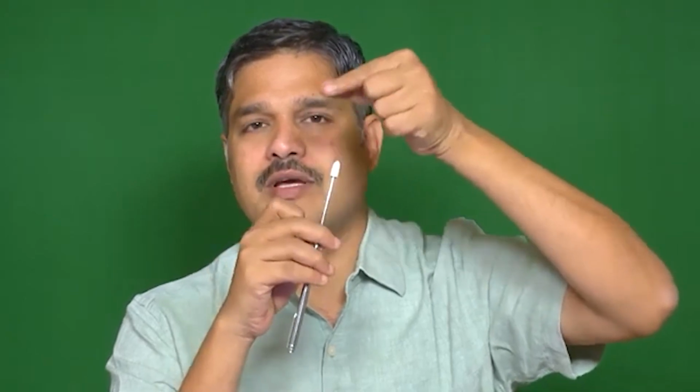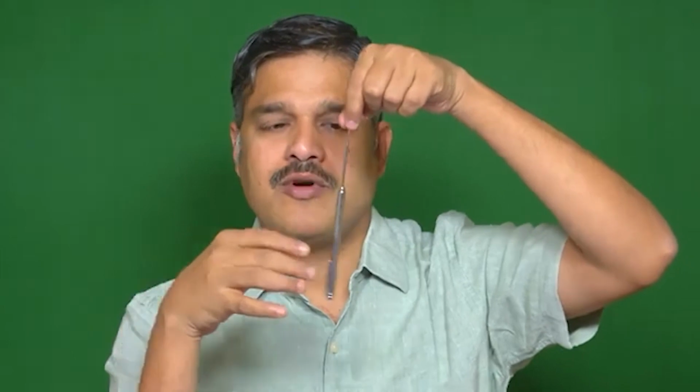It is dissipated in two forms. One is friction between this edge and my finger, that's friction. In the form of heat it is getting dissipated, and the second one is air resistance. So in these two forms the entire energy that I am supplying for oscillation is getting dissipated. So this is damping. In a way, damping removes the vibrating energy, and in each cycle it removes some.